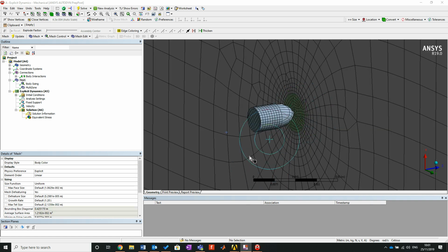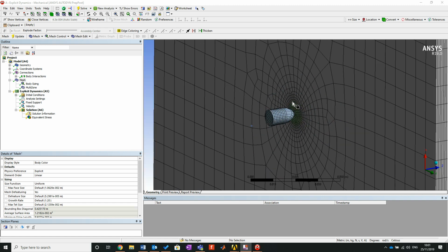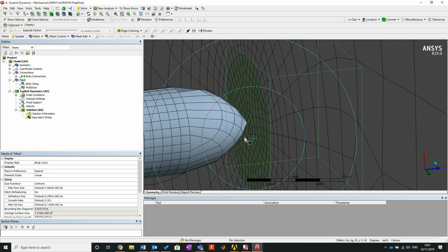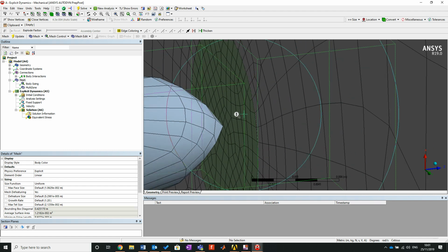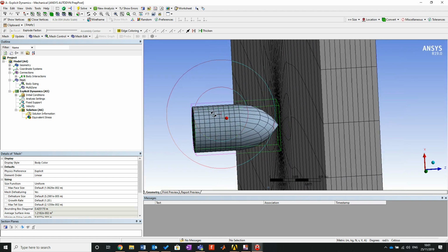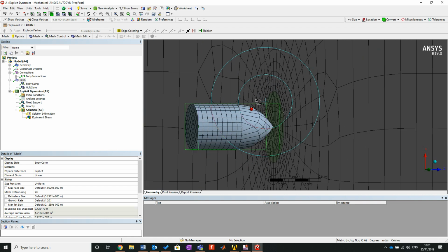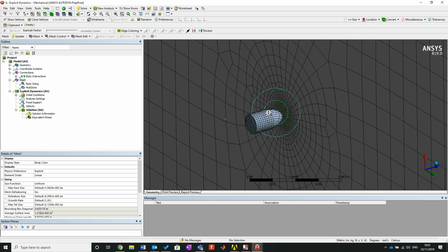Right, what you'll have found is when it ran, you probably came up with a problem saying time step too small. So what does this actually refer to? This is referring to the iterations between two behaviors. Basically, as it's coming into contact, it doesn't talk exactly as you'd want it to. So it says, well, if I can't converge, it must be down to the time step, hence why it brings that back. So I've now gone back in and made some modifications.